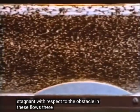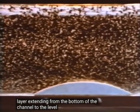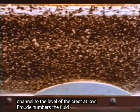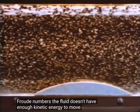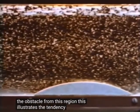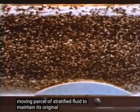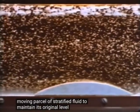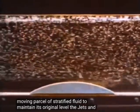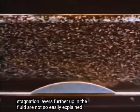In these flows, there is always a stagnation layer extending from the bottom of the channel to the level of the crest. At low Froude numbers, the fluid doesn't have enough kinetic energy to move up over the obstacle from this region. This illustrates the tendency of a slowly moving parcel of stratified fluid to maintain its original level. The jets and stagnation layers further up in the fluid are not so easily explained.